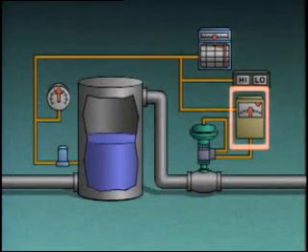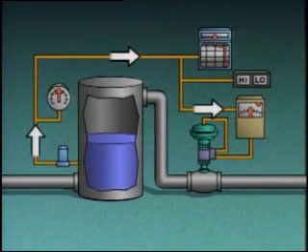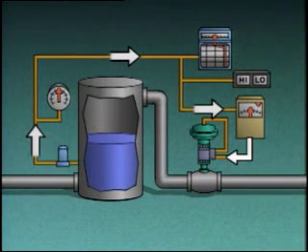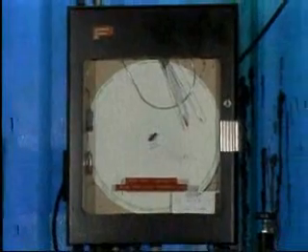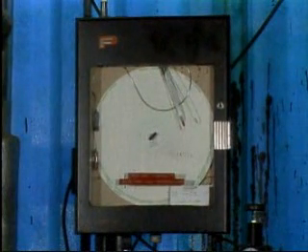The controller in this water supply system controls level. It operates by receiving a pneumatic signal from the transmitter, comparing that signal to set point, and sending a pneumatic signal to the final control element if necessary. So it can be referred to as a pneumatically operated level controller. Some controllers have a chart to record process variable values over a period of time. This controller could be called a recording controller.